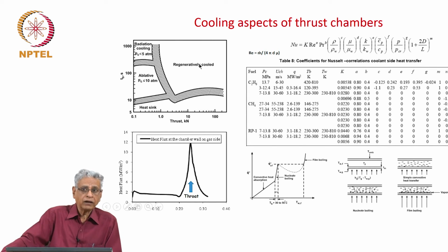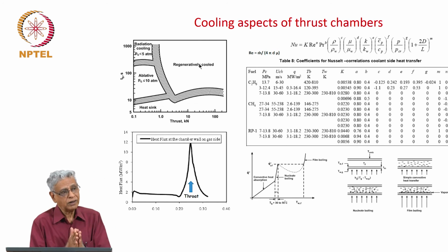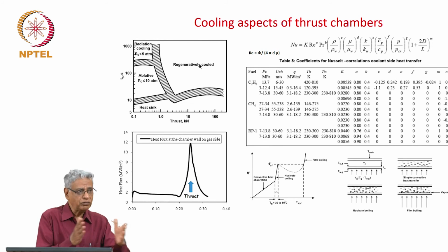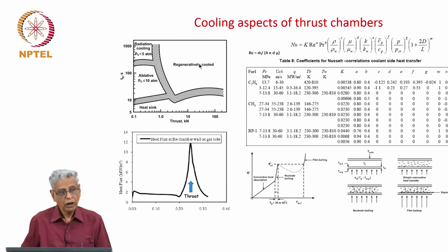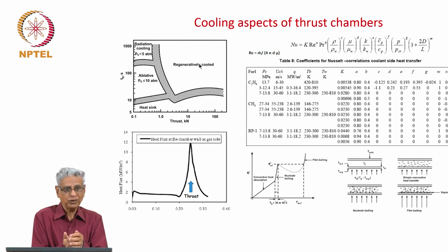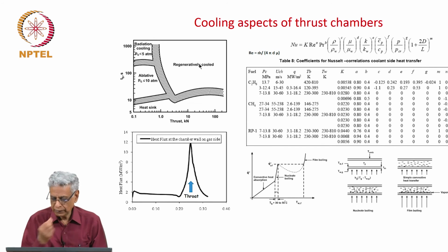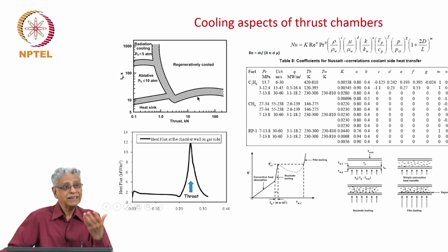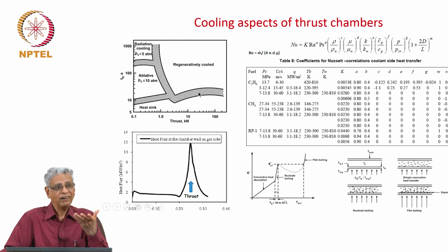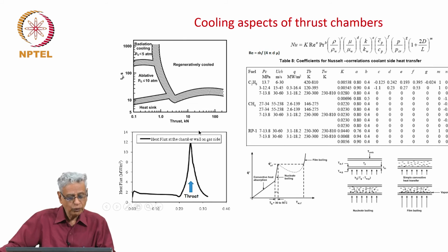In point of fact, for the gas engine, there were debates at some point of time whether to convert that into a regeneratively cooled system. Which means that it is a borderline case between one or the other. If you had done regenerative cooling, you would have gained in terms of performance, because the liquid would have been heated, pumped into the system, so we gain. Okay, it's a matter of design ultimately and the choices you make in the development of a system. I am just mentioning to you a key point here.